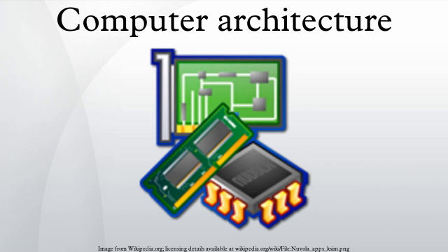There are two main types of speed: latency and throughput. Latency is the time between the start of a process and its completion. Throughput is the amount of work done per unit time. Interrupt latency is the guaranteed maximum response time of the system to an electronic event. Performance is affected by a very wide range of design choices. For example, pipelining a processor usually makes latency worse but makes throughput better.